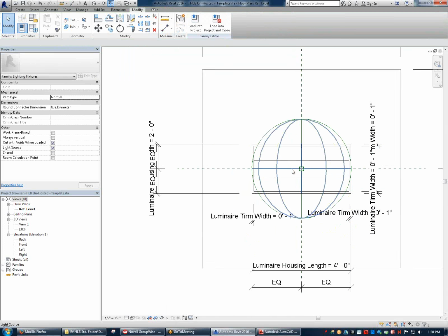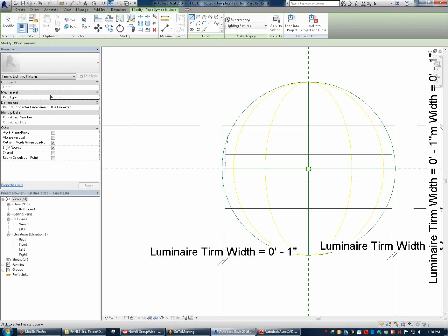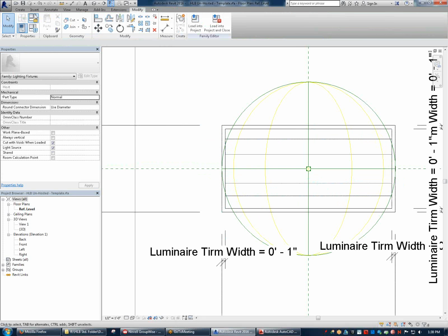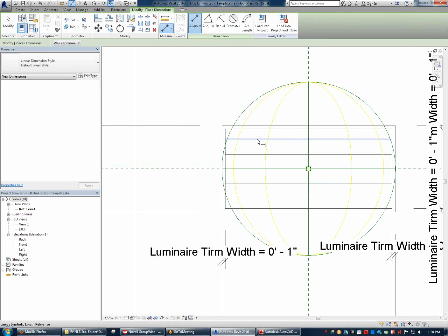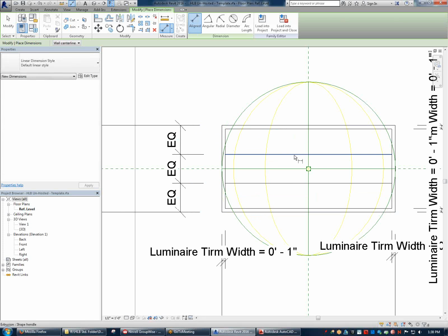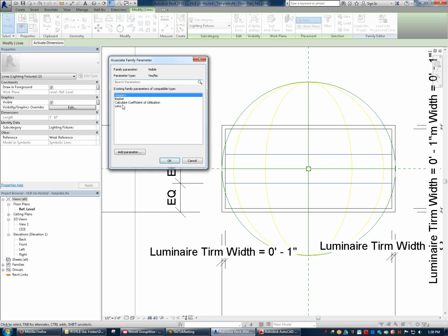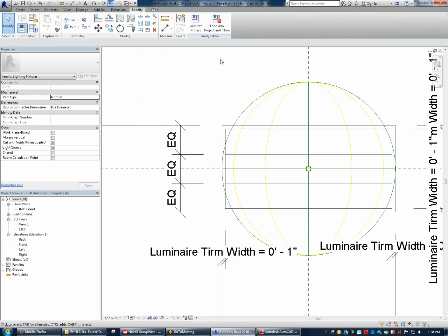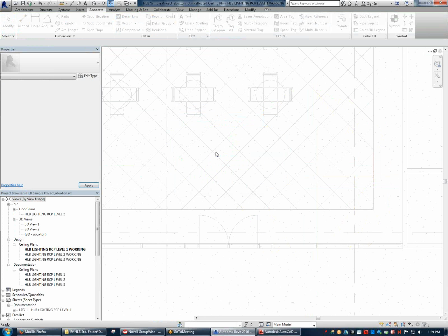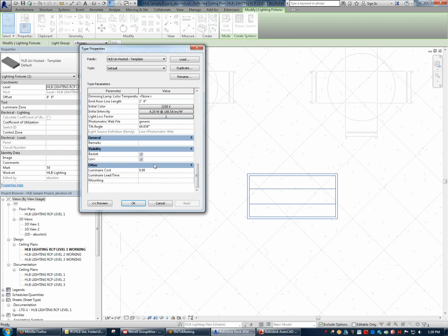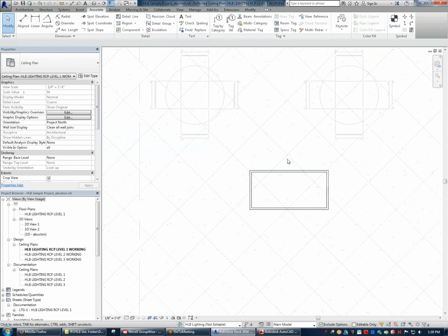Trim width. Okay. And then the last step would be our basket, which is just going to be 2 lines. And we're going to do the same thing we did before. Equal. Okay, and again, we have to make sure that these only show up when we have the basket one selected. So I select the 2 lines, I go to visible, I select basket. So now, when I load it in, there it is. And when I uncheck basket, there it is.